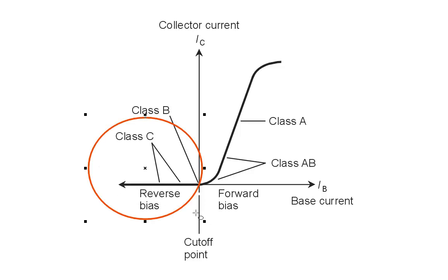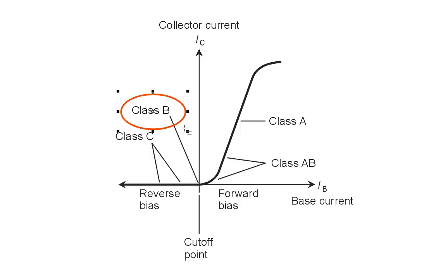We do not want to use that class of operation for single sideband because it will introduce nonlinearity into the waveform or the modulation envelope of the signal. Now there's a difference between linearity and a radio frequency power amplifier, which can occur. We can get that with class B, we can get it with either class AB1 or AB2, and we can get it with class A. We can't get linearity in a radio frequency power amplifier with class C operation.